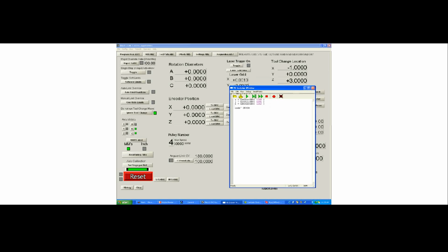We're going to do this at rapid speed. And we're going to first move the Z up to its coordinate. So we're going to put a Z and a quote, and this is typical Visual Basic script, an ampersand to join whatever we put there to the Z, and a Z. Now if we were to test this program, what should we get? Well, the X, Y, and Z that we've just read into the program is equal to -1, 0, and +3. This means when we execute our G53 G0 Z with a Z, it's going to take us to Z3.